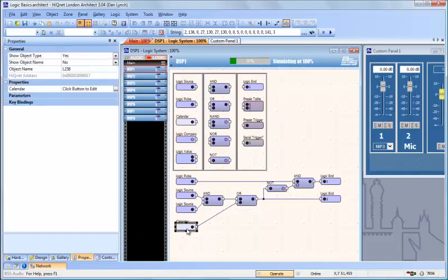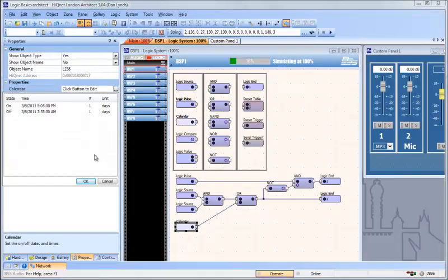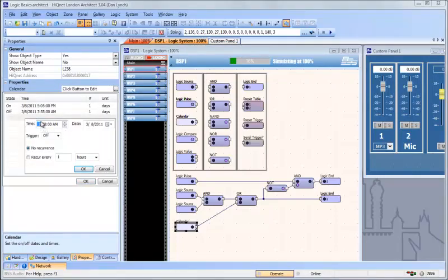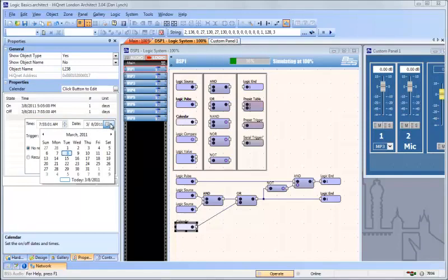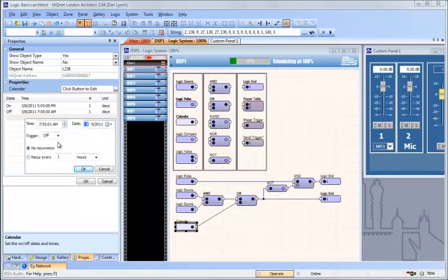They even went one step further, because in the calendar object, we can have overlapping triggers. In other words, I can double-click, program a trigger for 7:55 and 1 second a.m., starting on Saturday morning, to turn the master mute on and recur every 7 days. Now, on Saturday mornings at 7:55:01, the system is going to remute itself. It'll unmute at 7:55 and mute again at 7:55:01.